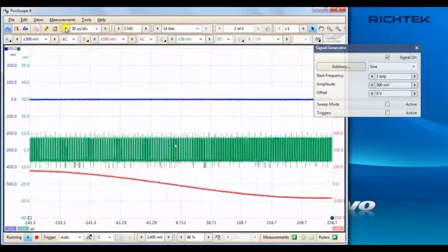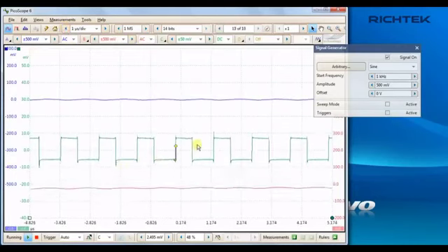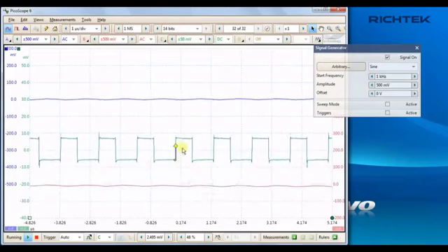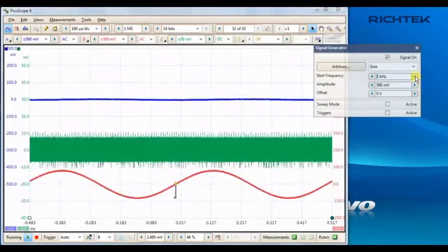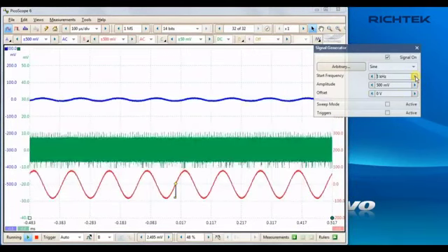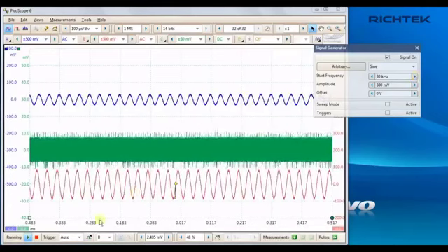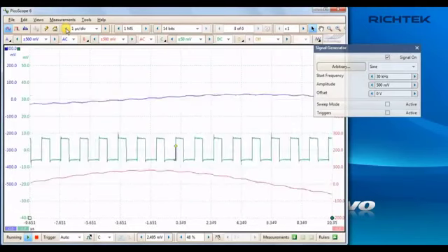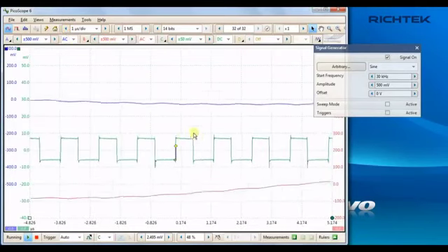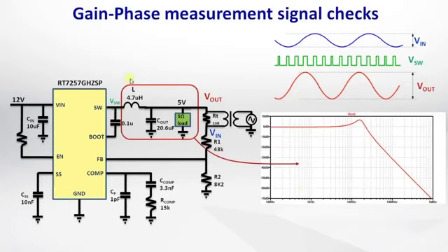When you trigger on the switching signal, you can see that at 1 kHz injection signal, the converter duty cycle hardly needs to change to generate the 90 mV peak output signal. Let's increase the injection signal frequency. You can now see that the converter input signal slowly increases, which means that the loop gain reduces. Above 30 kHz, you can also see that the switching signal duty cycle varies more. This is caused by the attenuation of the Buck LC filter above its resonance frequency. At higher injection frequencies, the converter will need to increase the duty cycle swing to generate the sine wave output signal.